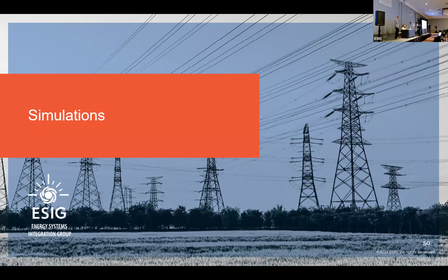And then, for example, you mentioned we can go back and change. But in ERCOT, for example, they're trying to implement 2800 right now, and they have so many inverters already that they are looking backwards and saying, I need inverters to do this and that, even those that are already there. Theoretically, yes, it's possible, but logistically, it's very complicated. Every generator owner needs to get in touch with the inverter manufacturer and talk to them about what it takes to make changes to the control loops to perform however ERCOT wants them to.